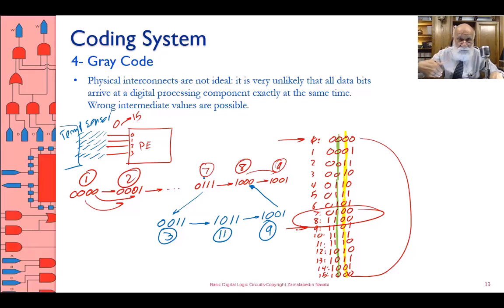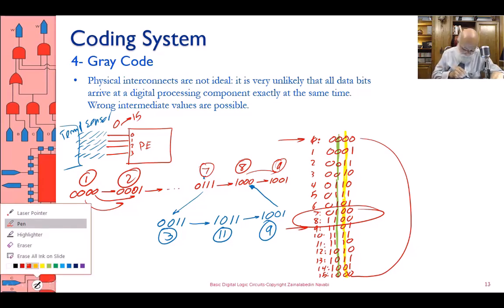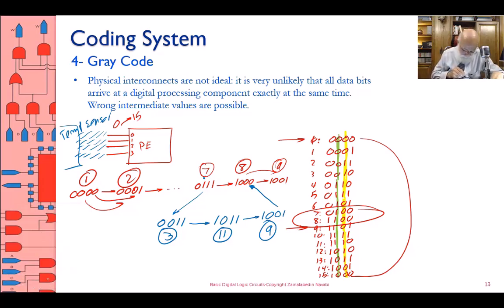When you go from 9, roll over back to 0 so that the next digit increments. Then from 9 to 0, you have 3 bits different. Look, you have 3 differences here. This is 9. This is 0. And therefore, between 9 and 0, you have 3 differences. And therefore, you have the same problem. That's if you are doing BCD.